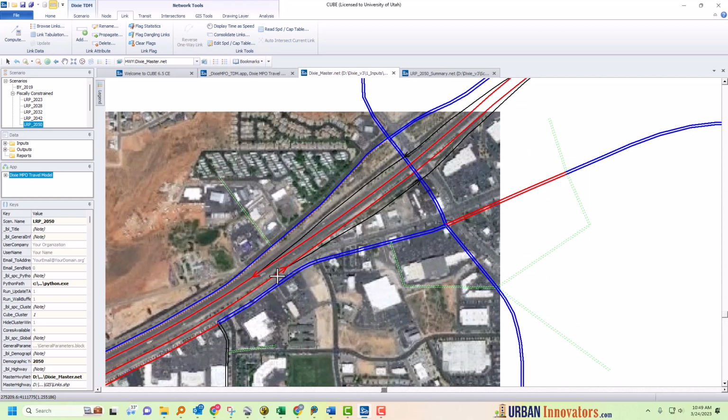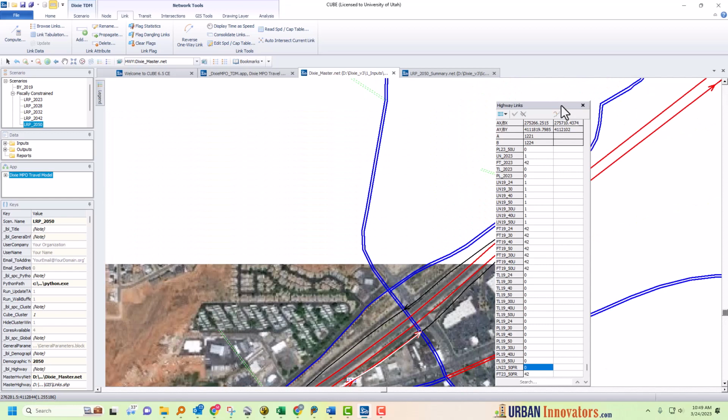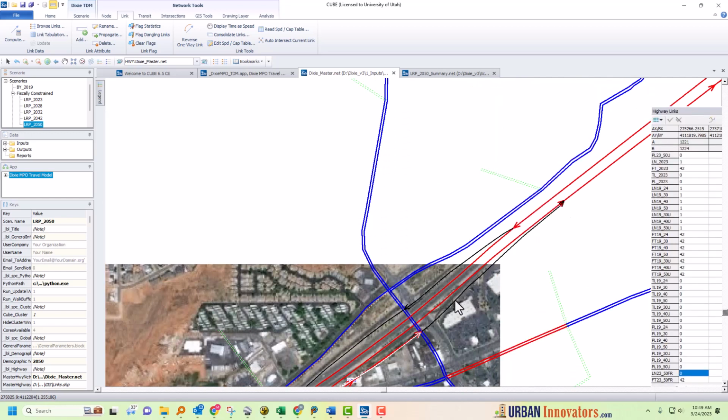The next thing I want is I'm going to copy, control V, and starting at this point, I'm going to go down like this and drop one right there, and I'll go right here. And okay, that's a good place to stop for that. Now I've got to turn off this ramp right here, so this is going to be a 0 now. And now I've hooked into the interchange, and then that's kind of the end of my system. So this can go ahead and be a ramp, but I want it to be a 2-lane ramp, like that, and rather than just a 1.